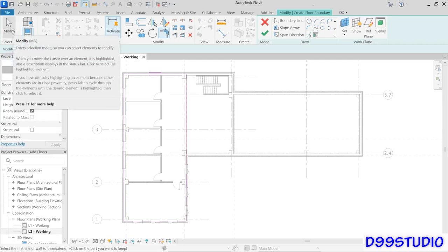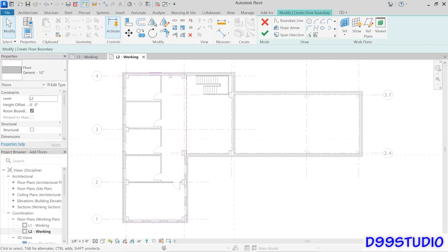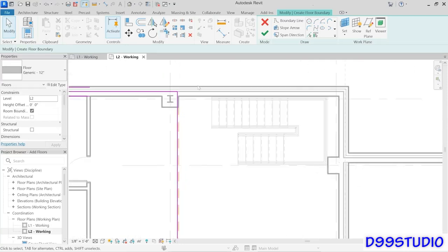Now, I'm going to click the Modify tool to finish and zoom in here at the stairs. This is a valid sketch, and I could click Finish Edit Mode. The trouble is, somebody coming up the stairs here wouldn't be able to get across to this landing. So we need to adjust the shape of this just a little bit more. What I'm going to do for this is here in the toolbox, I'll scroll up and I'm going to just use the straight line tool.